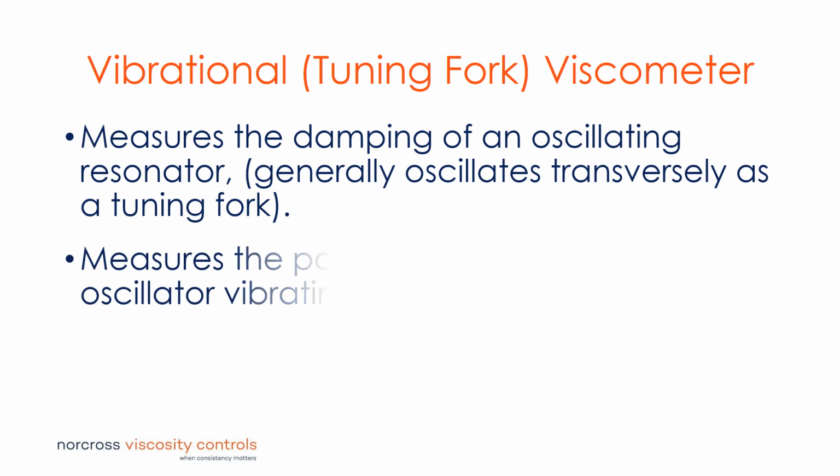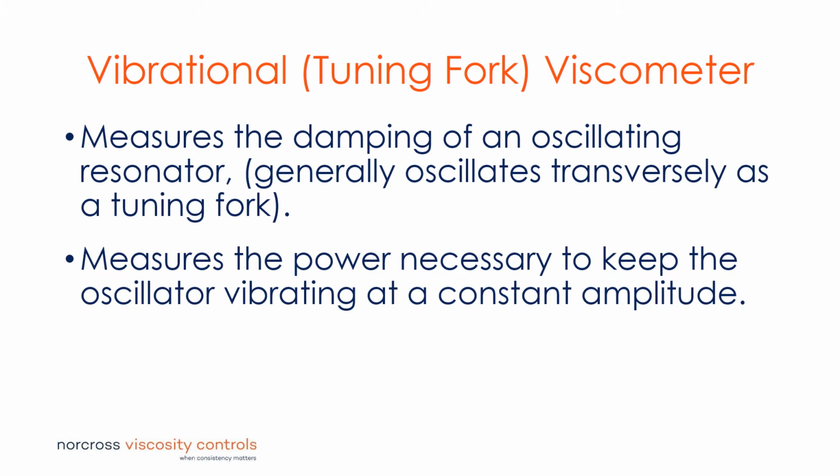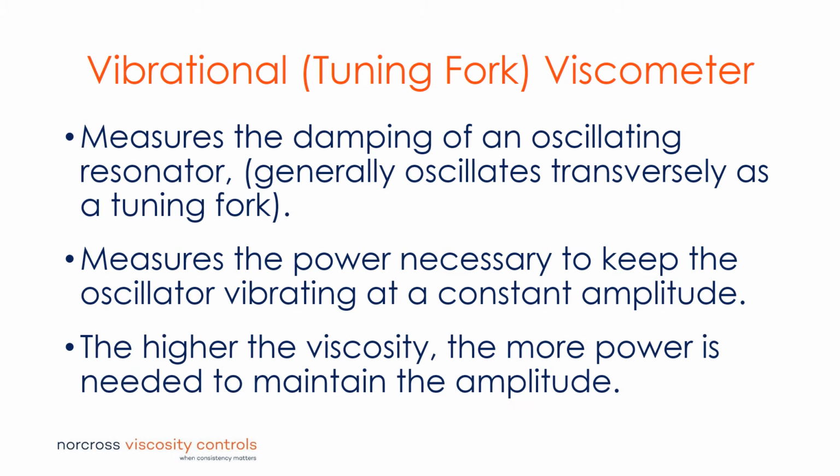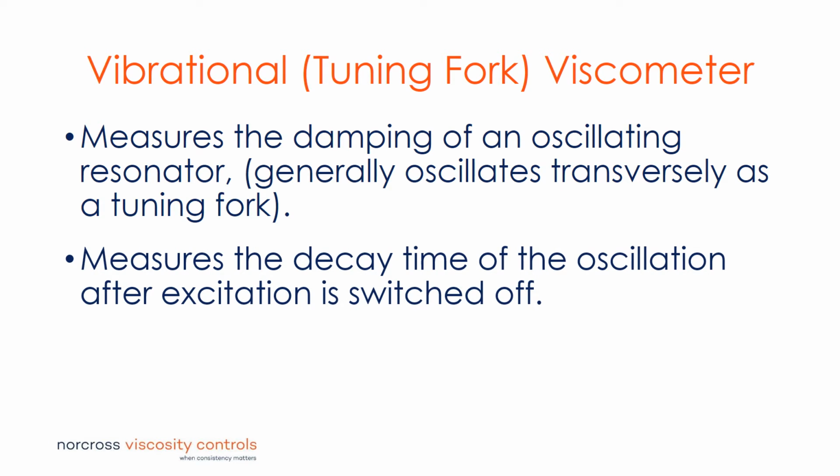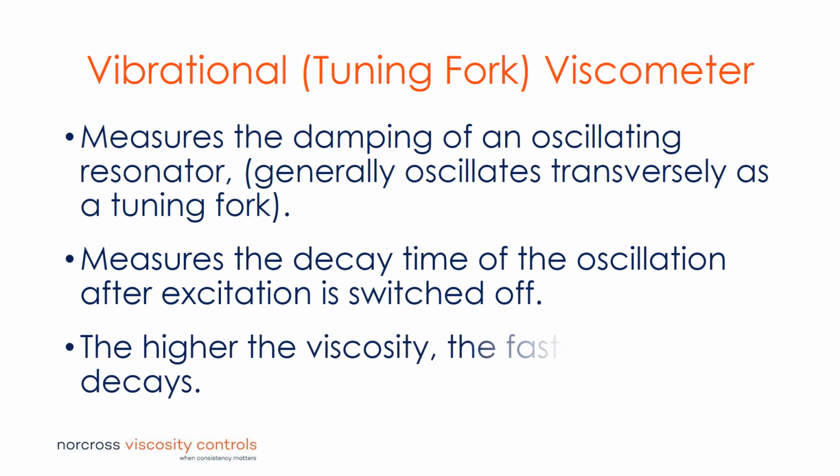First, measuring the power input necessary to keep the oscillator vibrating at a constant amplitude. The higher the viscosity, the more power is needed to maintain the amplitude of oscillation. Or measuring the decay time of the oscillation once the excitation is switched off. The higher the viscosity, the faster the signal decays.